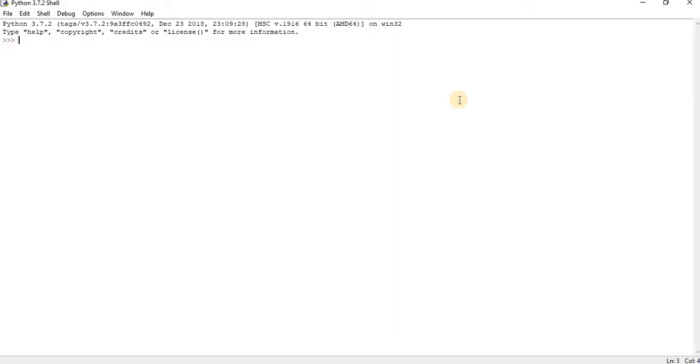Like most programming courses start with the first simple program of Hello World, we will start our civil engineering or structural engineering programming with a simple program just to determine the type of the section, whether the section is under reinforced or over reinforced, because it is very important to determine the type of the section, as IS code does not allow any over reinforced sections. So let's write our first program for a singly reinforced beam.